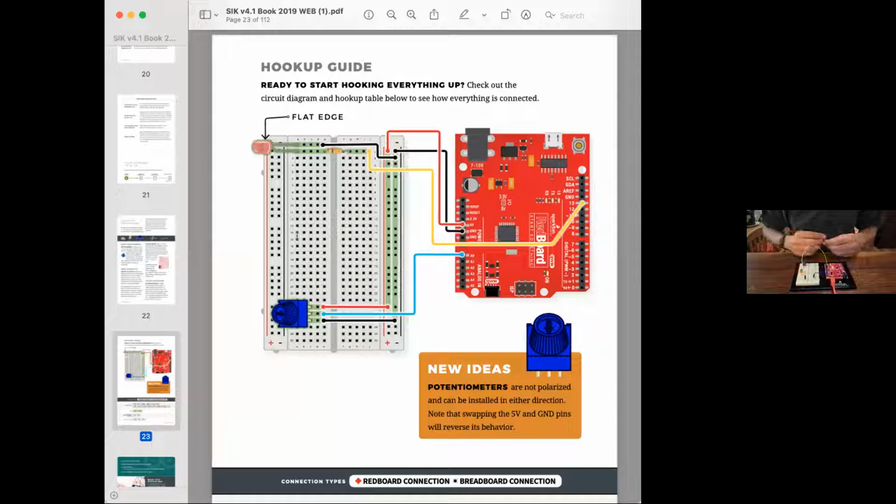One thing that we can do with the breadboard, which is usually very handy, is that on the edges here, the ones that go up and down in the vertical direction, what you often do is you'll make one of them be positive. So in this case, we're using 5 volts. So one of them will be the 5 volts rail here, and the other one will be a ground rail. That way, if you ever want to get to 5 volts or to ground, you'll just put a wire from your breadboard to one of those columns instead of having to go back to the board itself.